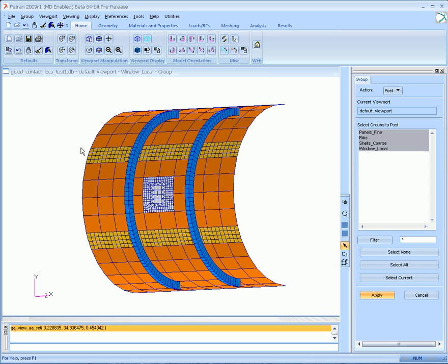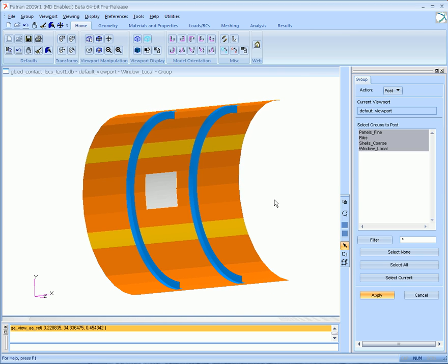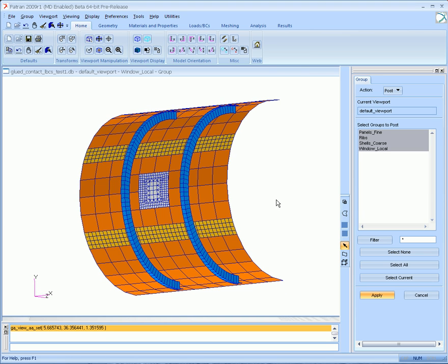coming from different sources that may or may not have a common nodal boundary to match together and create a model that will be glued together very quickly to make an assessment on performance or even integrate a local modeling within the primary master assembly and avoid having some standalone models and worrying about transferring loads properly, and also retain the stiffness boundary conditions all around as part of the main assembly. So there are no changes or drastic differences or assumptions made when you do that.